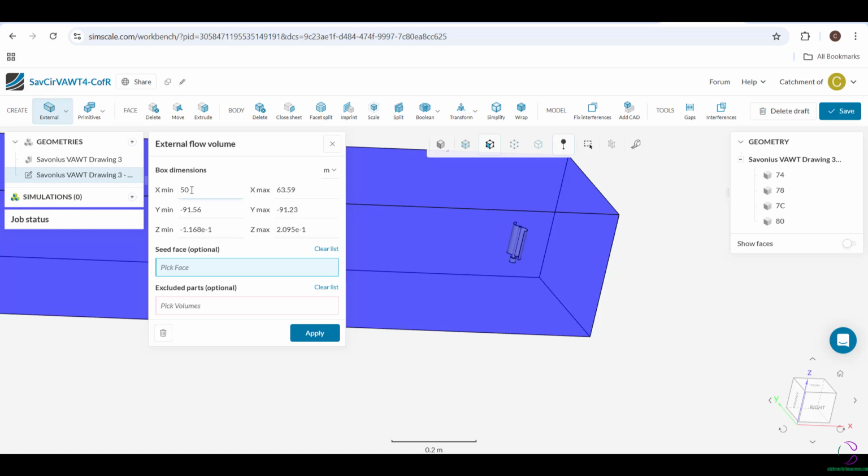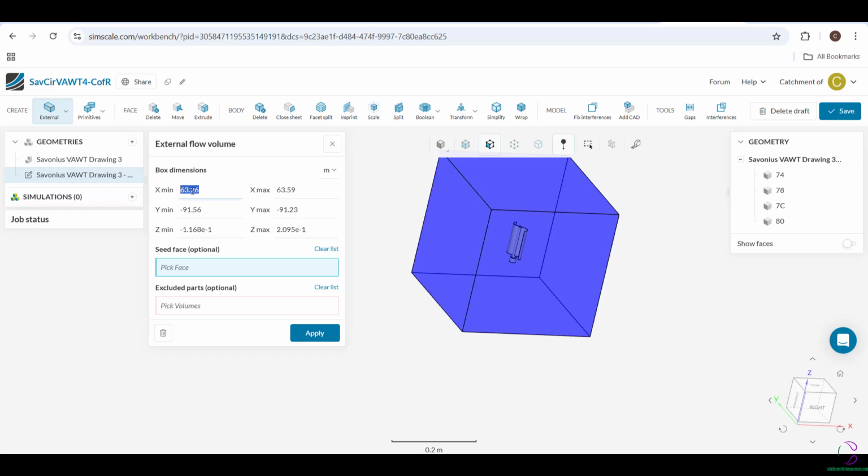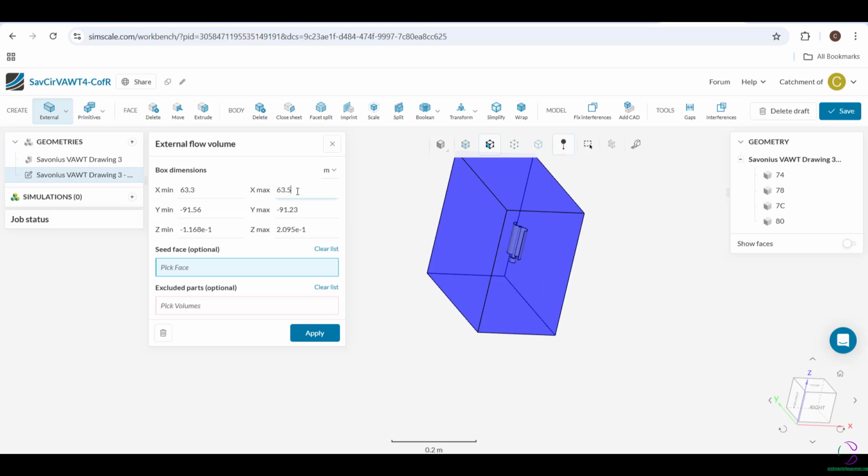It's possible to actually validate this on site. For example, if you are using a wind tunnel and you apply wind to the Savonius VAWT, you will see the point where the wind is largest at the wake. You can then take your sensors to pick up the value at that point to know whether it tallies with the value in CFD.